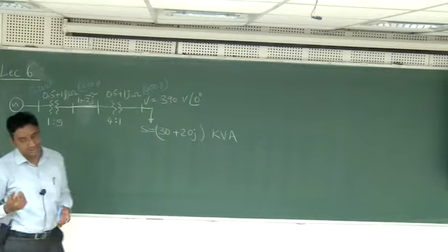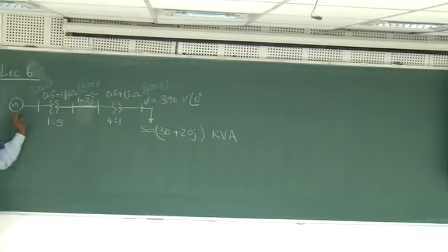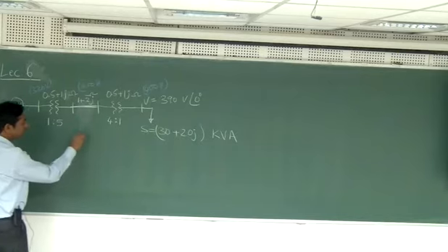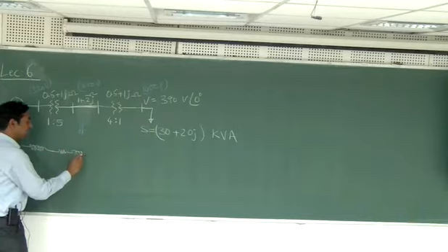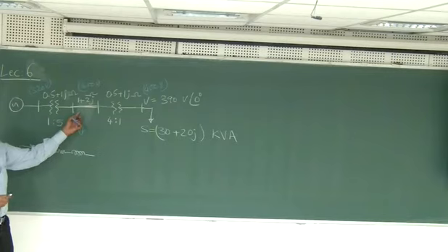But if you use the per unit system, what happens? This is your electrical power system single line diagram. You understand all these symbols. From this you create another diagram, the reactance diagram. This will become a voltage source, and there is no impedance of this generator. It's an ideal voltage, at least for this problem. Then there is a reactance, which represents this transformer. Then there is a resistance and reactance, which represents this transmission line.